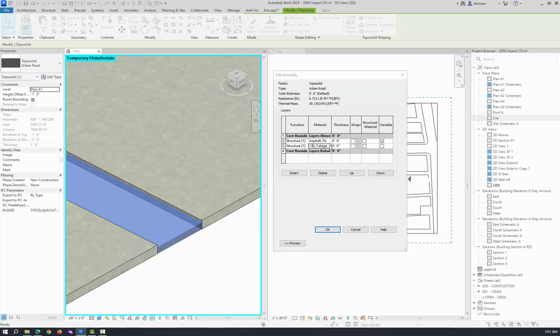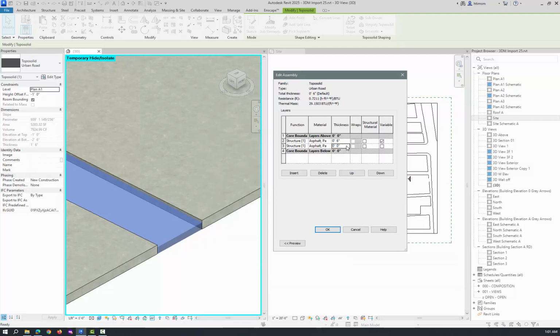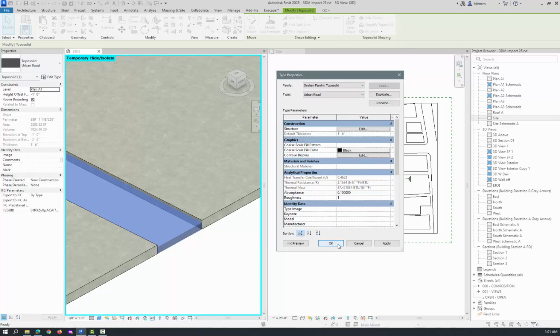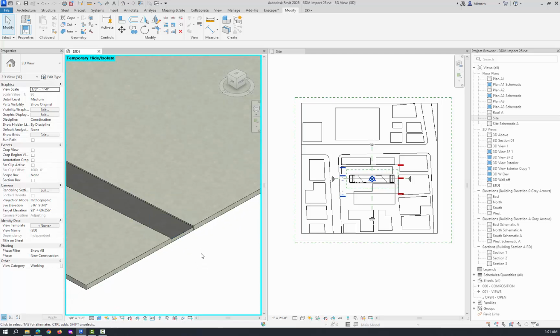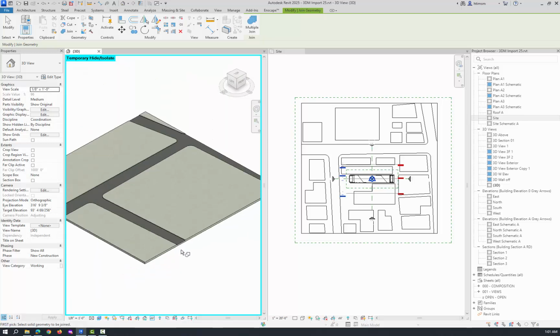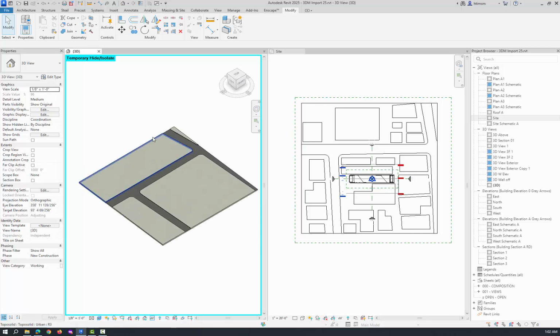And then I'll make this one, which I'll make the light gray, I'll make that 1 foot. Okay, and click OK. Right, and now I've got that condition, right, which is a little cleaner. You can also go in and use your join command to join these, right, and it will get rid of that line. So now I have a sunken, little divot pushed down road.